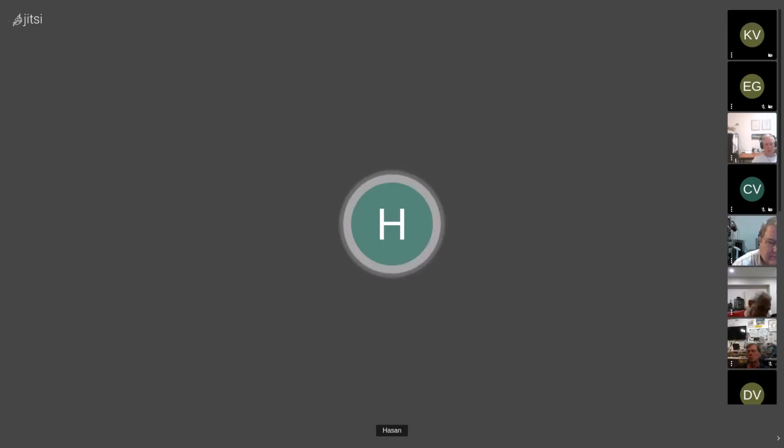Yep, I'll go next then. Go ahead. So, I just hooked up an antenna before this meeting. It's a vertical, about 30 to 40 feet high, and I hooked it up to a tuner. So my thought was it'll either be a lambda over 4 at 20 meters, which is like 33 feet, or a 5/8 antenna on 20 meters. I didn't cut it exactly, but I was just testing it out.